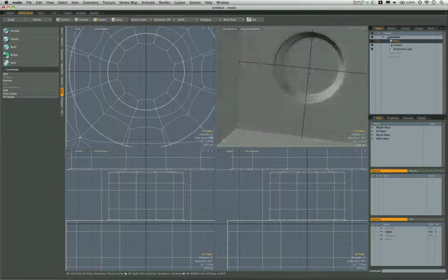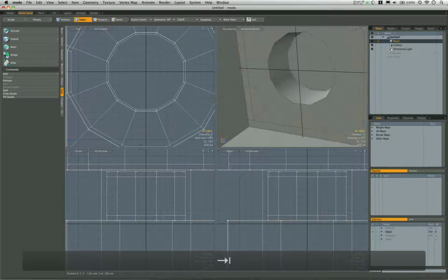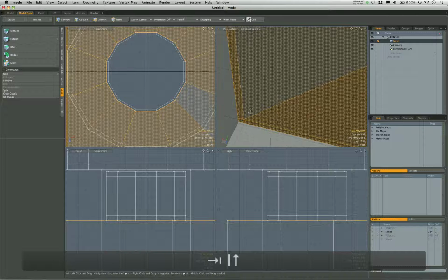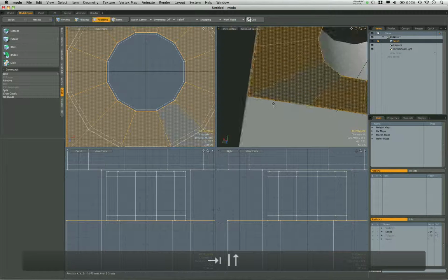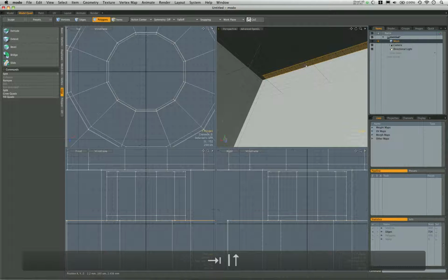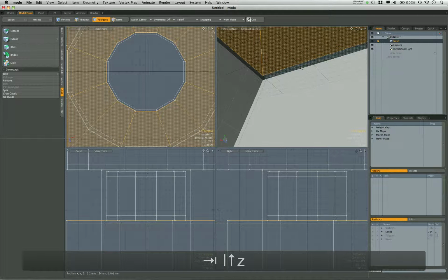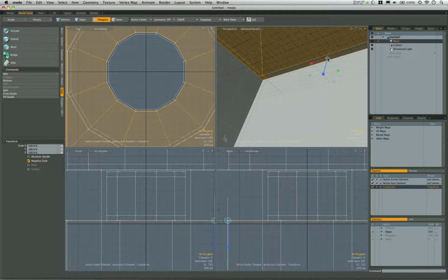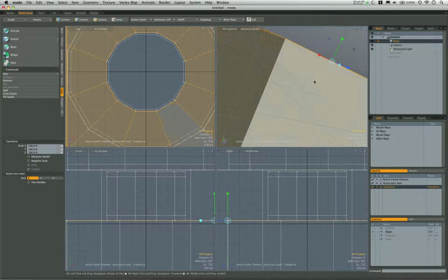And one thing we'll notice is that if we unsubdivide here, we have this loop and then this loop, and they're not going to be necessarily 100% flush with each other. So what I'm going to do is scale this, and I want to scale it relative to this outer rim, which is the rim that we haven't touched yet. So I'm going to select all those, do my scale tool, and I'm going to set it to an element action center. I'll just click on this one, and just to make sure I'm properly up and down, I'm going to change my axis to auto, and then I'll turn off negative scale, and I'll just flatten this guy out. Oops, if it will let me.